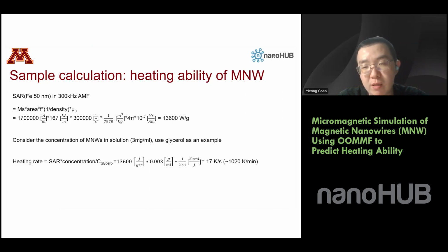So 300 kilohertz is a very low end of the commercially available values. And experimental measurements can show even better heating, because we will have a rougher surface and also rounded tips. Therefore, we can even have a better heating number for the real process.